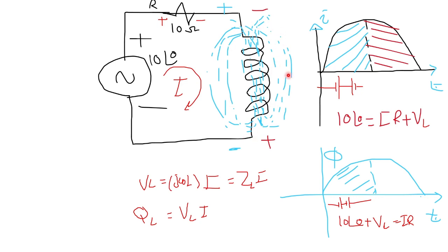The energy stored on the coil would be released back into the circuit. This means that the coil is not acting anymore like a resistor, and the voltage drop across the coil is not anymore like a voltage drop. Instead, it will act like an additional battery added to the circuit, whose negative terminal is connected to the positive terminal of the main voltage source.